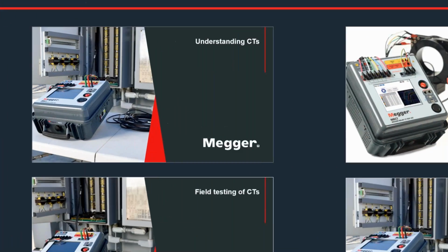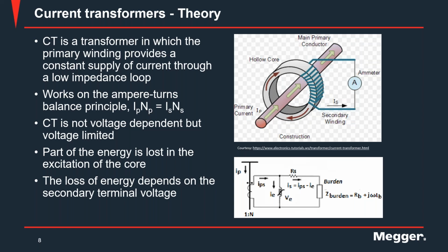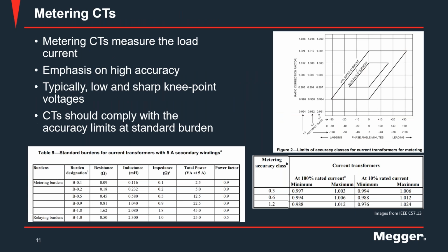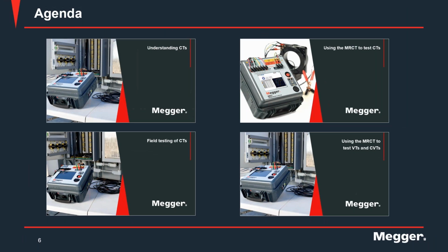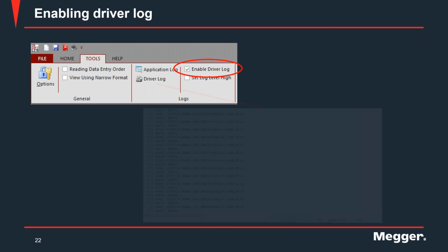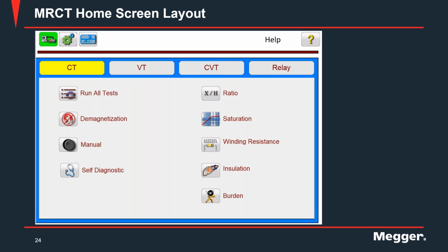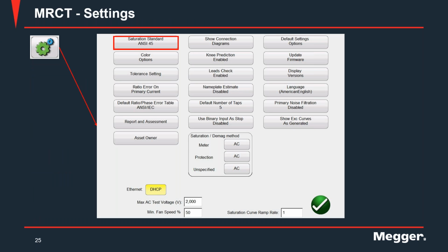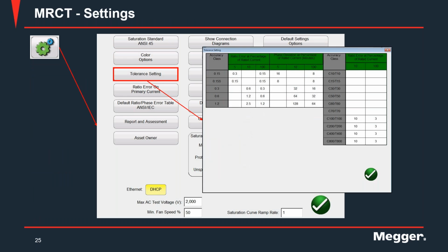And then what is the accuracy class for the CT? It is important that you fill out that information in the nameplate, so the software will help you with the assessment of the results. Once you get the measurement data, if you do have that information filled out, the software has a great feature called a CT assessment or nameplate assessment.